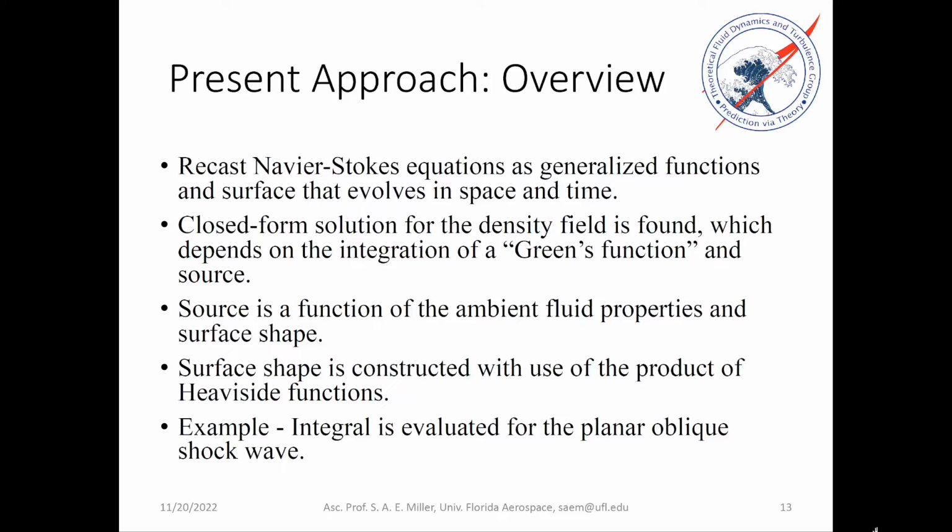We wish to recast the Navier-Stokes equations as generalized functions and integrate them about a surface which is moving arbitrarily in space and time. We will write a closed-form solution for the density, which will depend on a convolution integral of something like a Green's function, but this is a nonlinear equation, and the particular source.